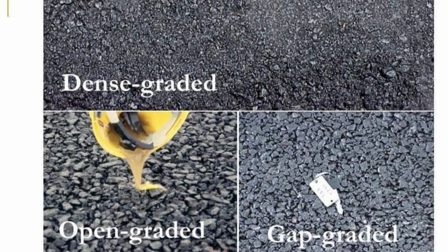Dense graded blends are also not good because they don't have space for the future compaction. Also, the open graded ones start the compaction later, due to which you will have different kinds of distresses in the roads.